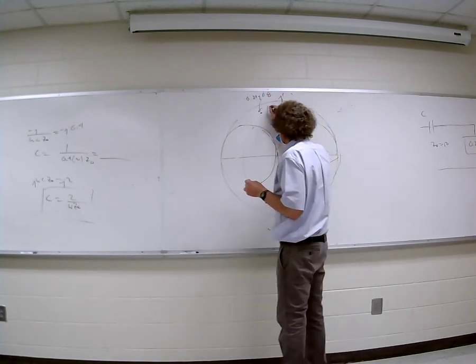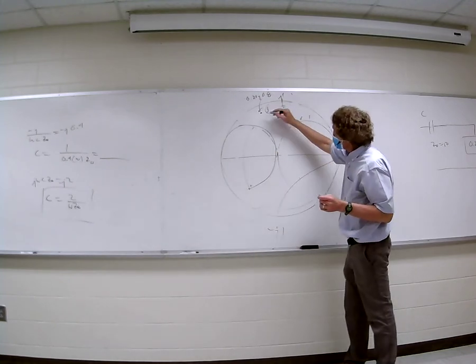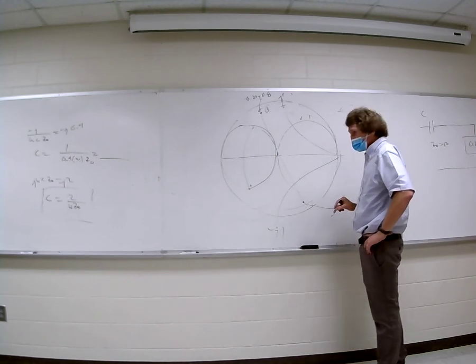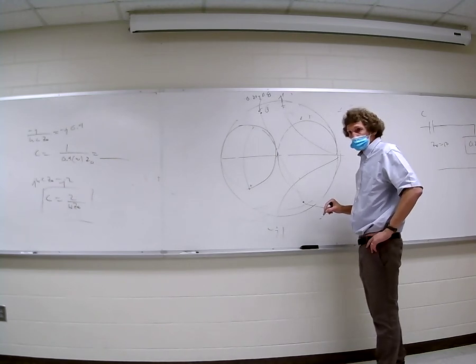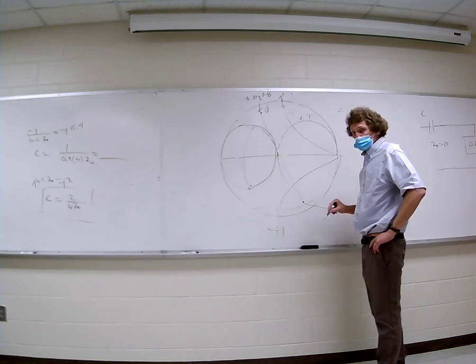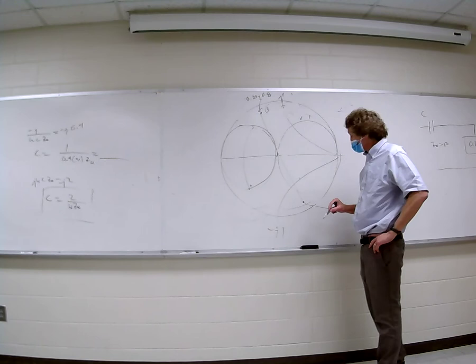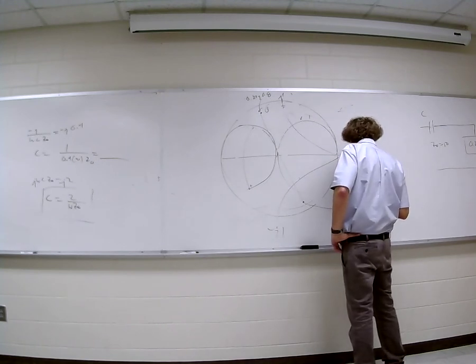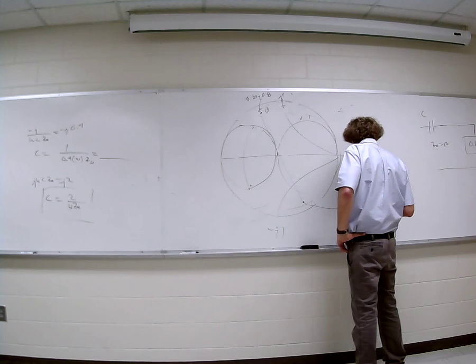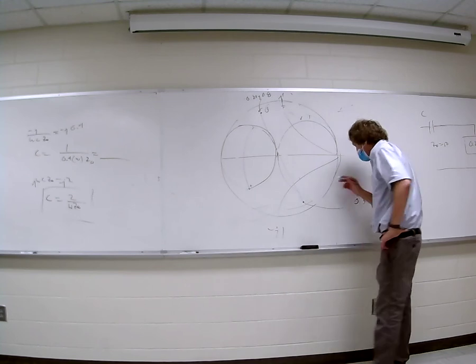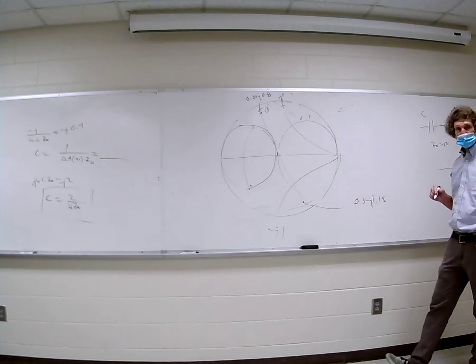That's impedance. If I go to the admittance domain, I pick 1 over that. I don't know where it is, but it's outside the 1 circle. It comes out to 0.3 minus j 1.18, and that's outside the 1 circle, right? Classic.